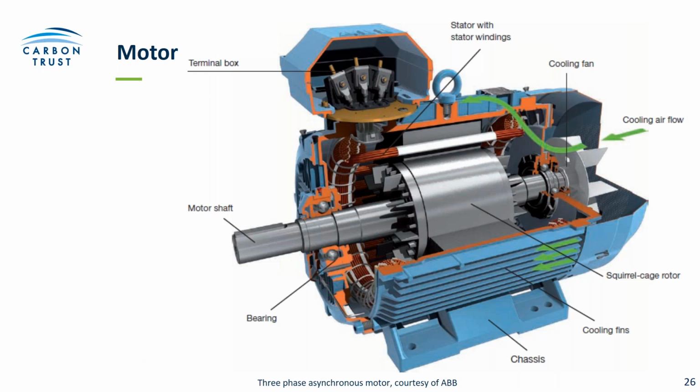So in terms of a basic motor, its speed will be determined by the frequency that the electricity supply to it is fed at. So that's often operating on a fixed speed basis, with that motor speed fixed by the frequency of supply. This example here is an asynchronous induction motor, which would be one of the more common types used. So effectively, to control the motor, you will need to look at controlling the speed of its operation.